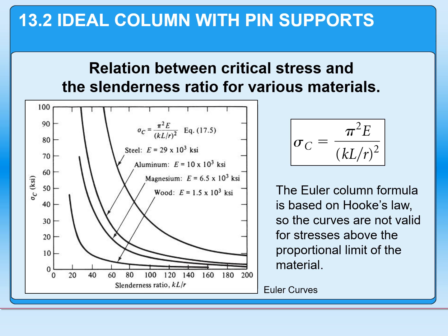Critical stress is shown on the y-axis, and we have a series of contour lines based on different materials, with wood at the bottom, with a relatively low modulus of elasticity, magnesium a somewhat stronger material, aluminum stronger than that, with a higher modulus of elasticity, and steel being the highest one we normally see. Essentially, this is showing this particular relationship in a graphical representation.